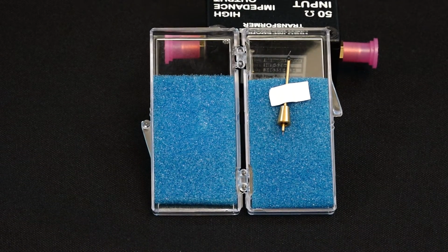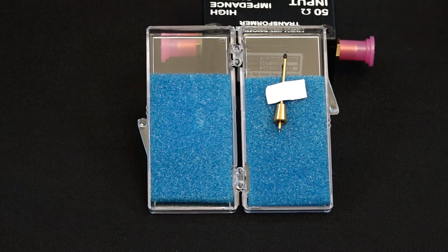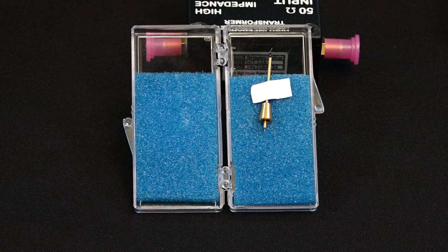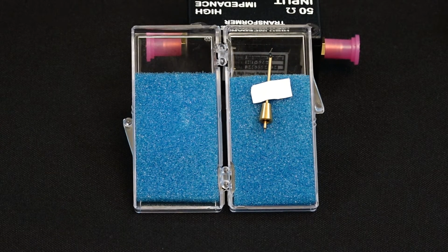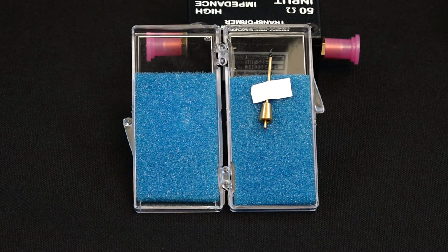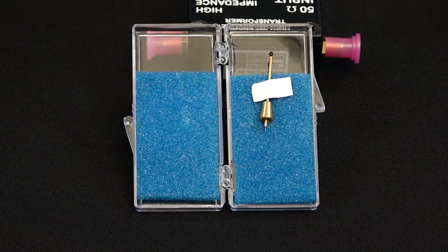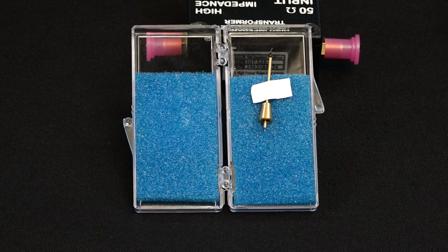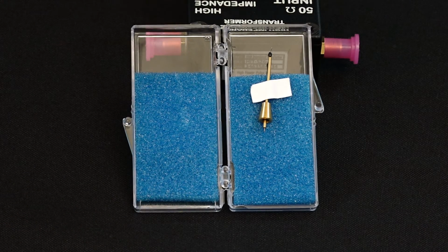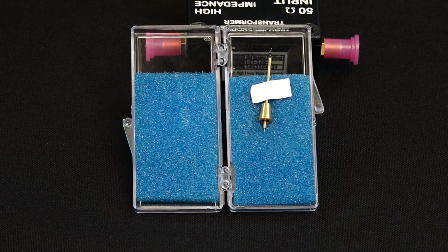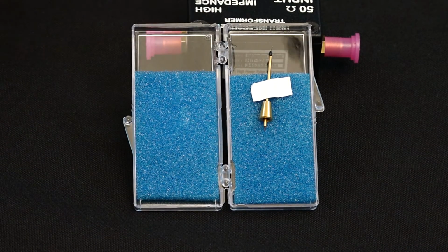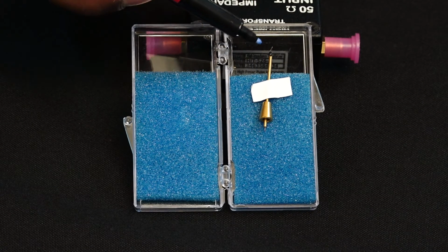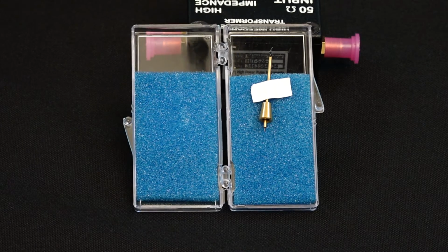So it's a 4 probe measurement, and these 4 probes will land on 2 different sets of contacts. You will have the signal contact of both the voltage and the current probe, and I'll discuss this in more detail when I do the measurements, and I think that will become clearer then. The signal of both the current and the voltage probes will land on one contact of the device, and the ground of both the current as well as the voltage channel will then land on the other contact. That contact is grounded. This is a typical probe tip that I am showing you here. I hope you can see these two signal lines here. One of them is a ground and one of them is a signal line.